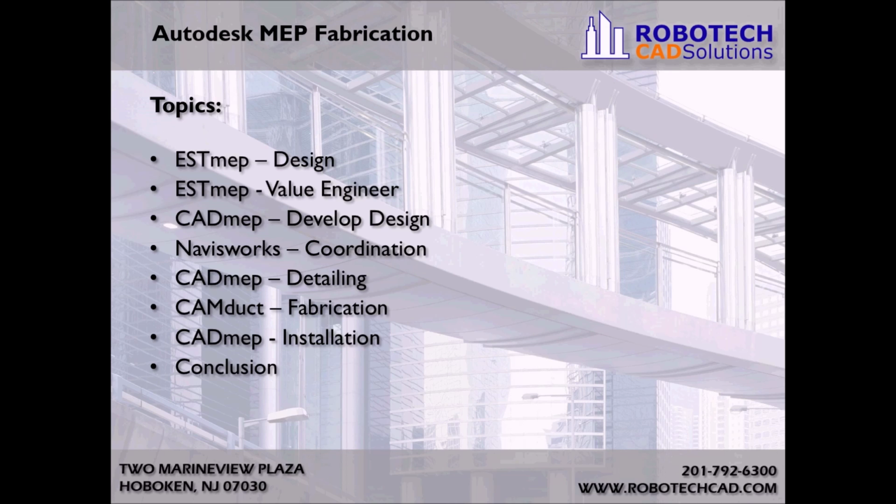And then we'll get into CADmep. CADmep will help us further develop the design, locate and solve conflicts, and detail the MEP components. We'll get into opening Navisworks for a few minutes, where we'll also use that as a clash detection tool between a structural model and the MEP model. And then we'll go back to CADmep for a little bit while we're doing some detailing.